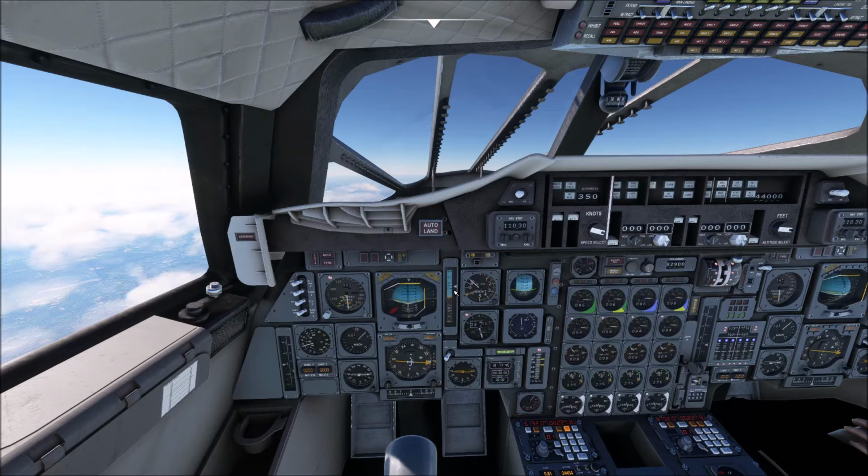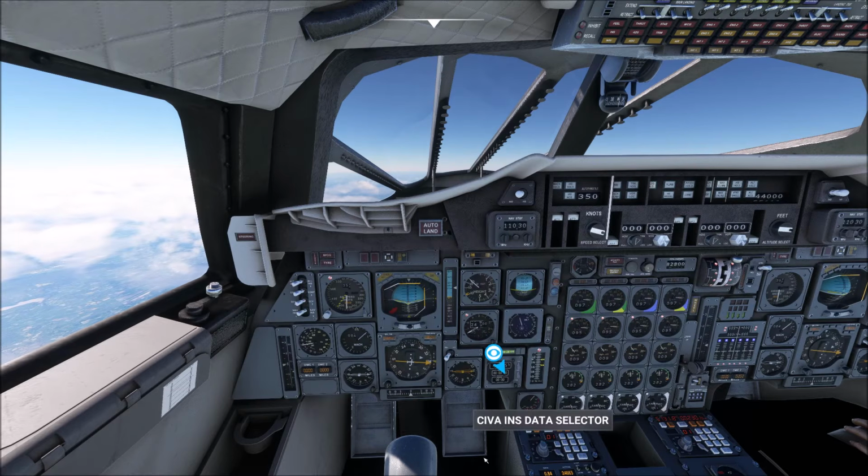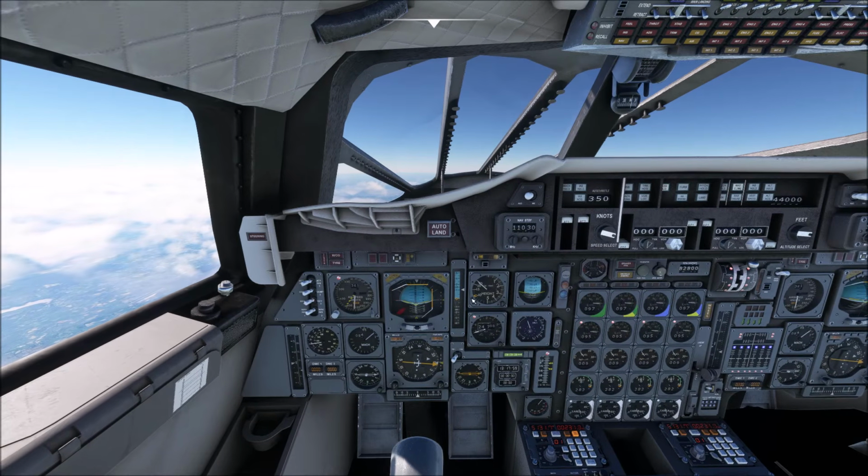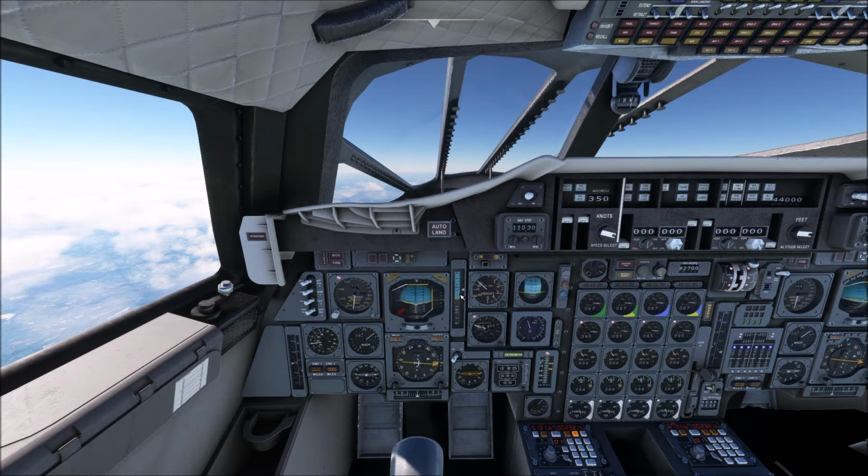It will move around depending on how much thrust is available. If it starts to slow down, it'll be climbing too steeply, so Concorde will automatically drop its nose, and it will do this all automatically for you. It's doing it now, taking care of business all on its own. Sometimes you'll only see 500 feet per minute climb rate. In fact, later on it probably will drop to that.